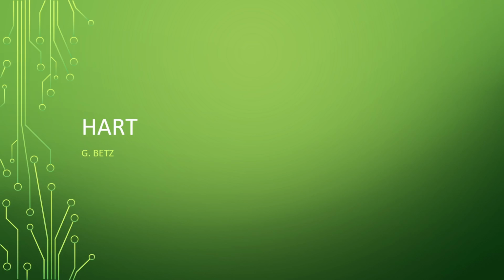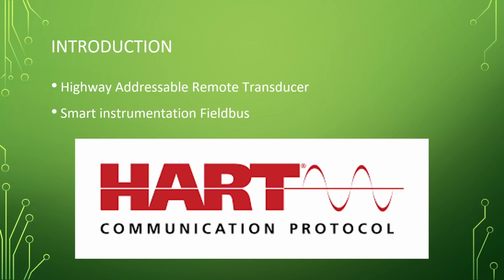Okay, so this leads us to the world of HART. HART is Highway Addressable Remote Transducer. And this is a smart instrumentation field bus. This is a protocol designed for applications where actual data is collected from instruments, sensors, and actuators by digital communication techniques. That's a mouthful, isn't it? So this will allow you to do things like diagnostics on your sensors, and memory for storing configuration or information, such as tag numbers, things like that.